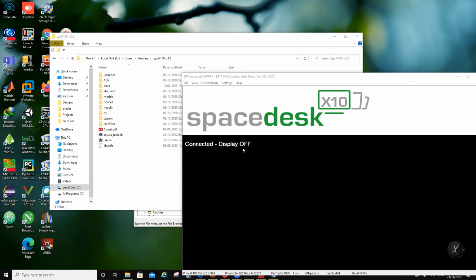And if you know post-processing, in Cadence, post-processing is going to be very difficult because there is a calculator there. There are some functions which you can write there, and it's through that. While here, there is a data display window. Anything you can write in MATLAB, you can write here, because it uses the same RFIC and BLAST libraries. So that's the advantage of ADS.